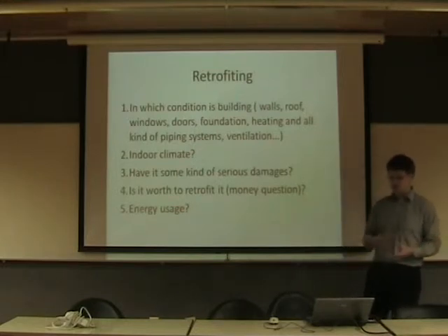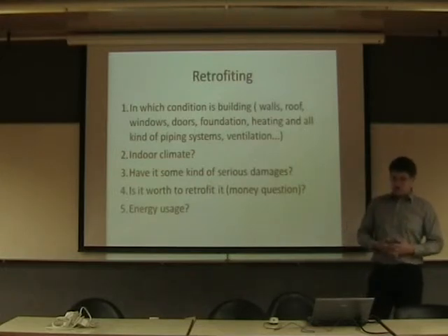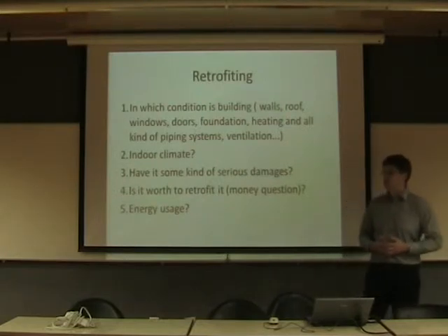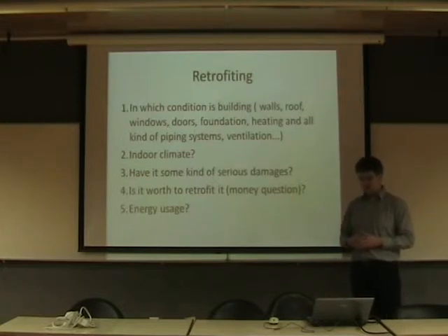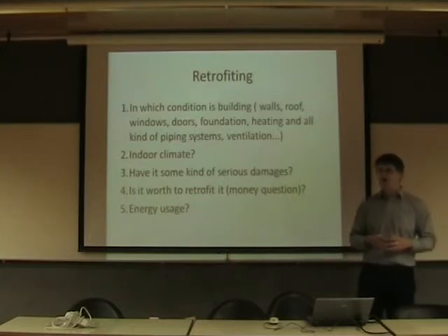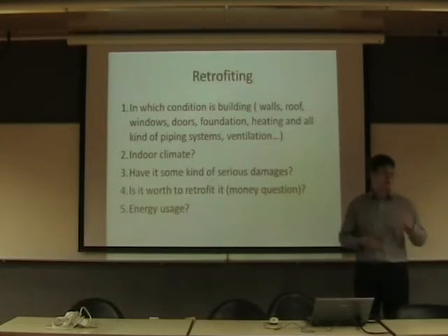We have a lot of the same kind of houses as this Lithuanian building, and we have also done some research work about these block houses, and the main damages are about moisture. They have condensation problems, they have lots of thermal bridges, or we say cold bridges because we have a colder climate.